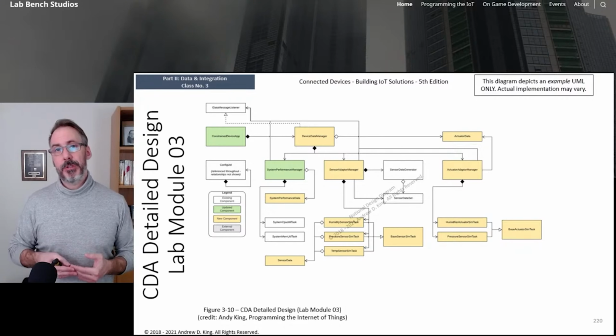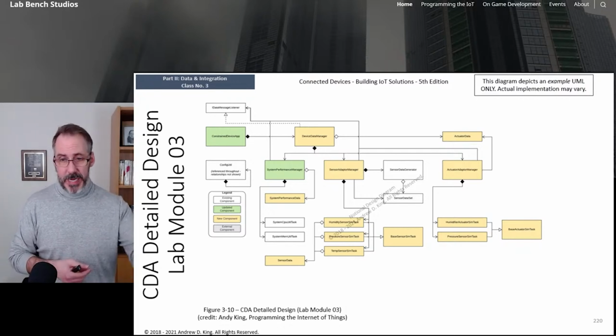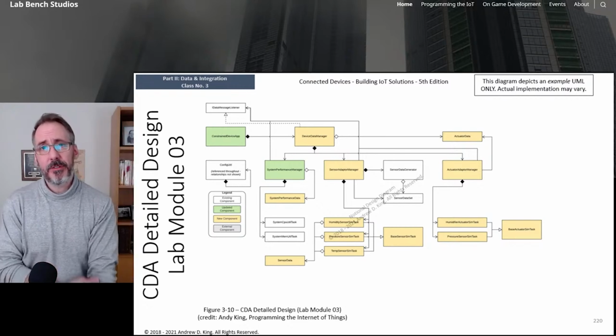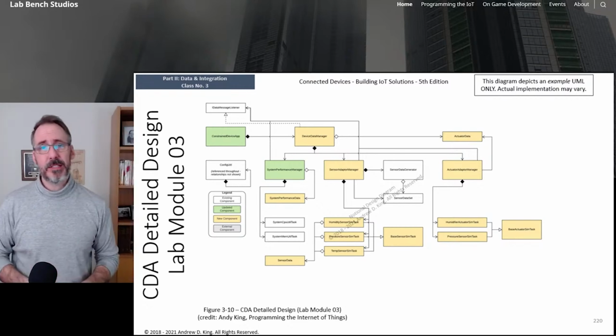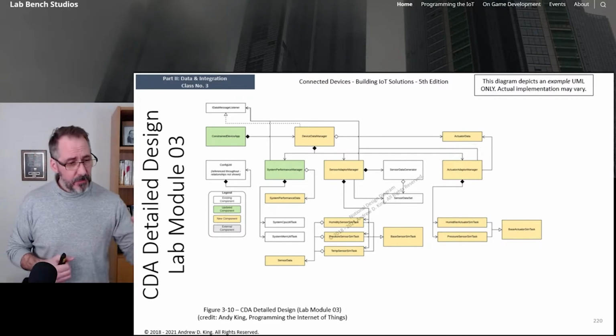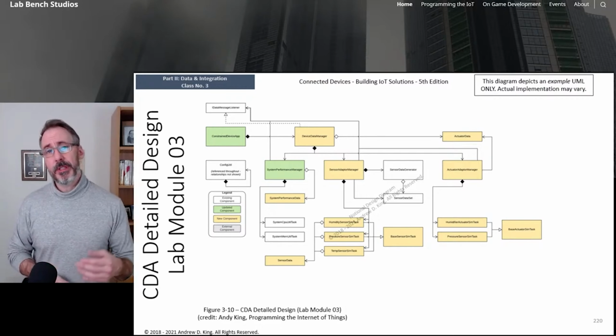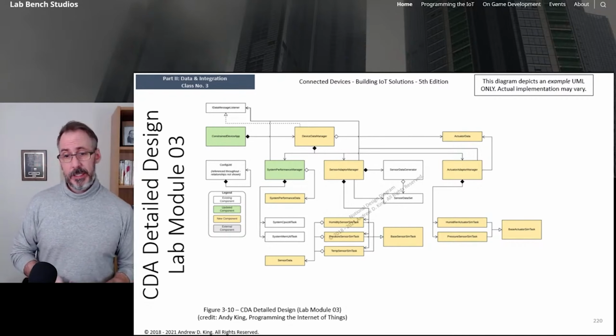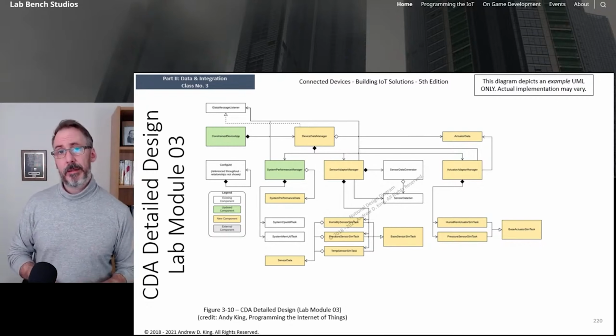Sensor Adapter Manager is going to manage threaded tasks or scheduled tasks that will read humidity, pressure, temperature, and frankly, whatever other sense values you want at a regular interval using the APScheduler library, which I reference in our examples and in the online GitHub repository and so forth.